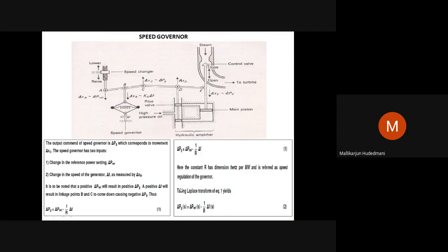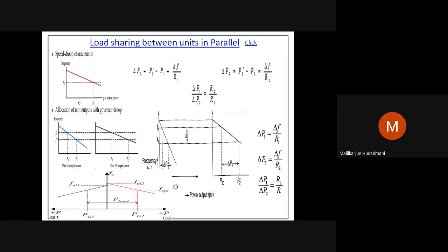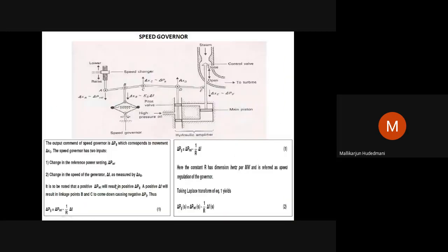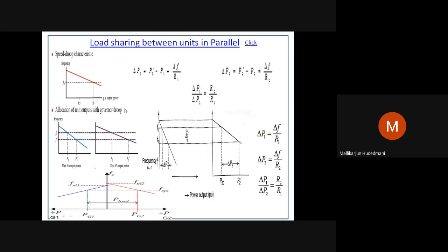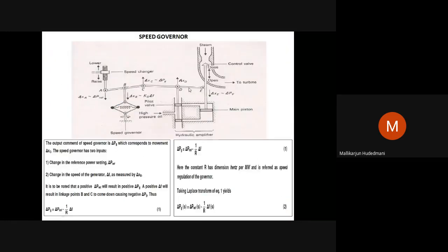So if I see how that comes into the picture, whatever governor I am speaking of, imagine it is the speed governor, which acts to control the fuel: hydraulic actuator, speed feedback and fly ball mechanism, speed set point, then your pilot valve and main piston and main operating point. If I connect these things, how is the valve opening and closing done?